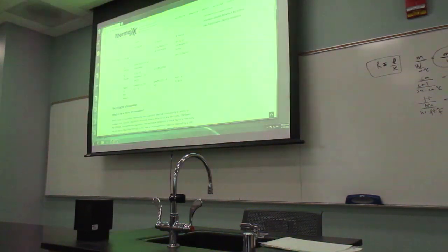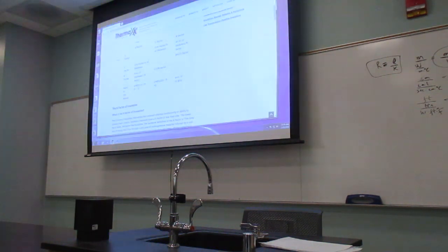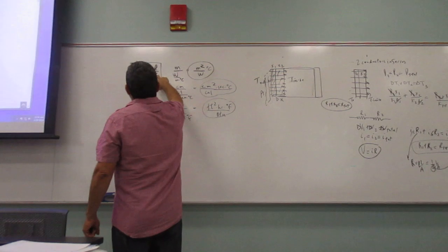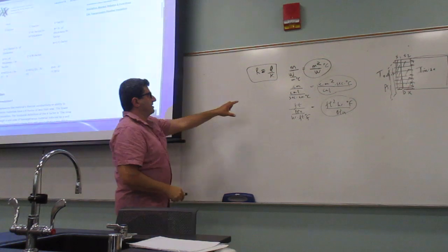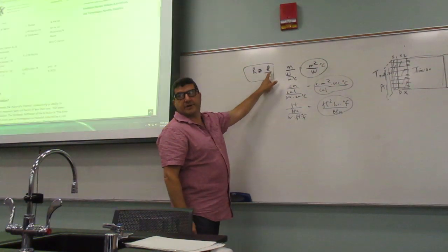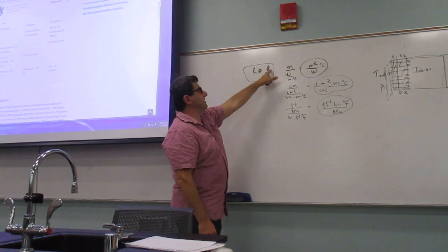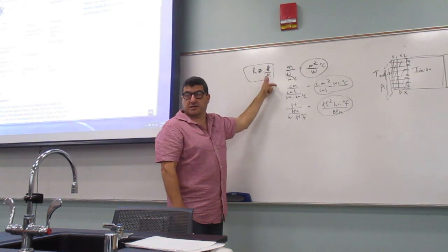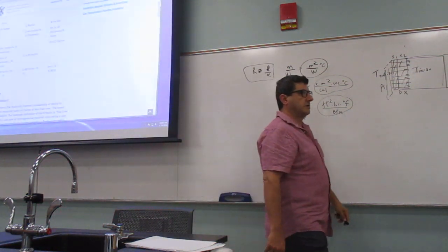So the K factor, let's see here. R factor. Well, the R factor is going to depend on the L and the K, but then the K factor, what they're talking about is probably just this thing. All right, the K factor is the bottom. And then what they say C factor, they probably mean the length of it. So, in other words, insulation depends on how thick it is, plus the K factor. So you divide one by the other.